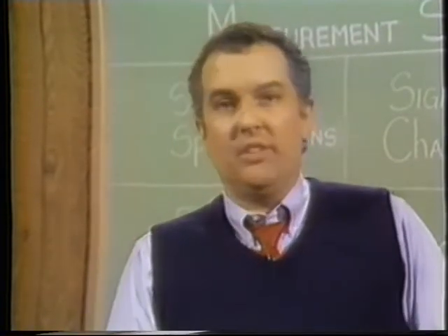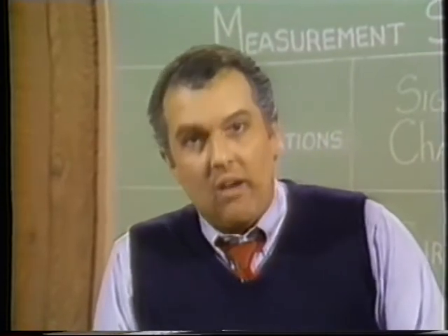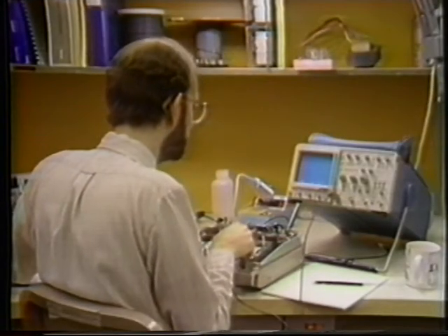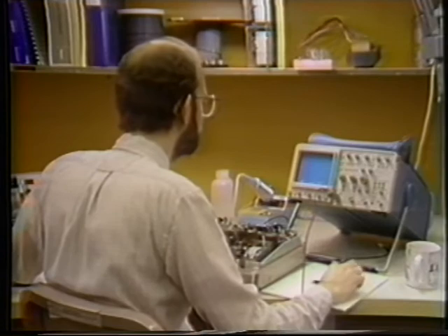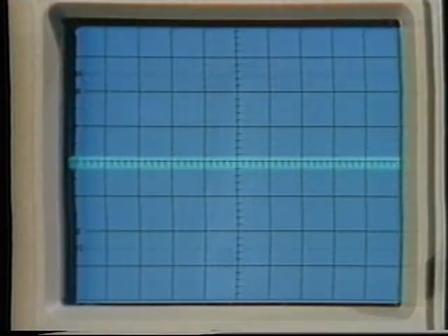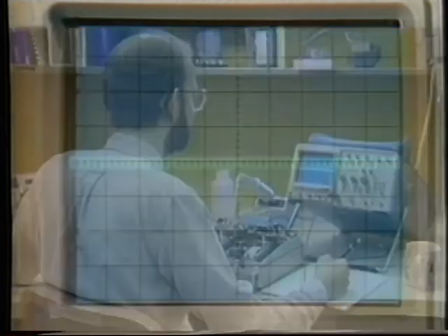Now, usually this isn't a problem. But there are applications when lowering the sensitivity of your measurement system isn't an option. Suppose you needed to view a 60 Hz low amplitude ripple on a power supply output, for example. At a 1 or 2 millivolt signal amplitude, the attenuation of a 10x probe becomes intolerable.